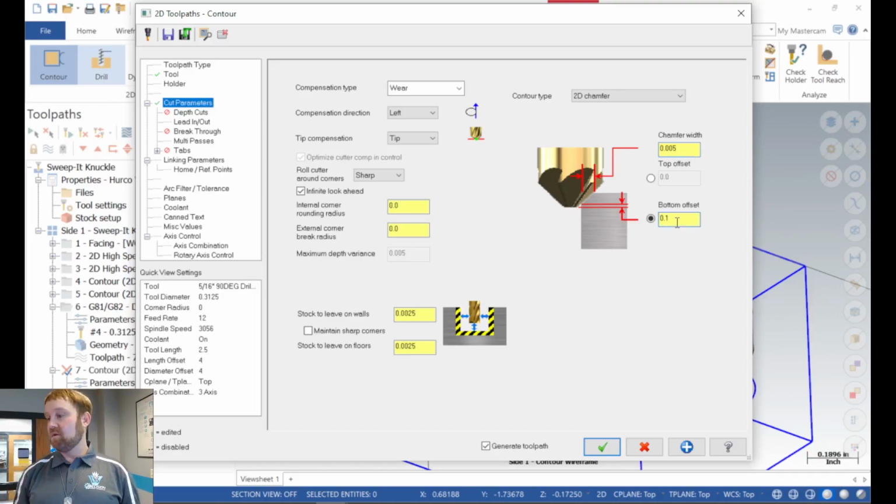Just because as you're going up with the tip comp, it's moving the tool closer and closer to center right on the edge of the part. Depending on what the width of that web is, if you get too far up and you go right there at that same point, it'll leave a big nasty burr at the bottom of your chamfer. It's not using just the side of the tool. It'll start kind of dragging the tip around there too. So